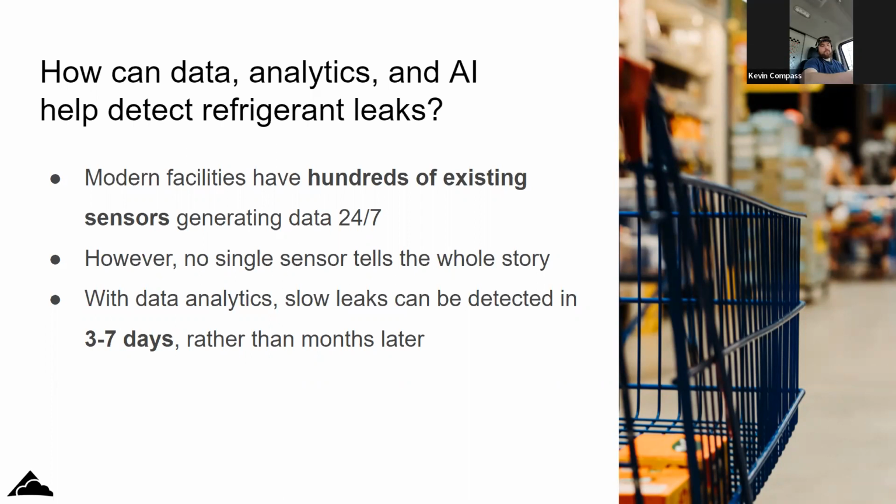For me, it really just depends on the store. There are some stores where huge leaks are common. The older the rack, the more stressed out all the piping is, so big leaks seem to happen more the older it gets. The smaller leaks come in with newer stuff, where there are case controllers everywhere and 200, 300 plus transducers. I start to see smaller leaks in those: a packed angle valve leak here, another packed angle valve leak there, a transducer leak here. It really just depends on the store setup.